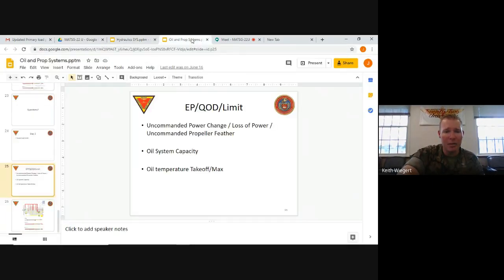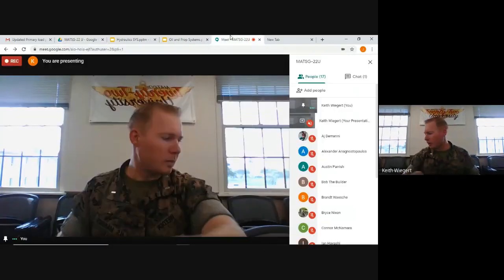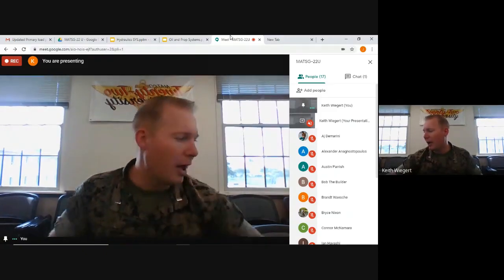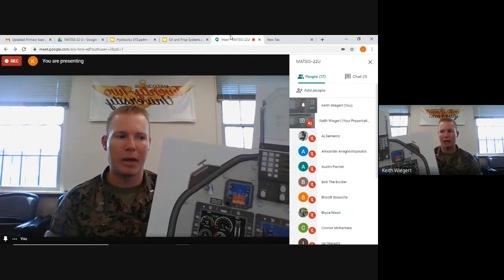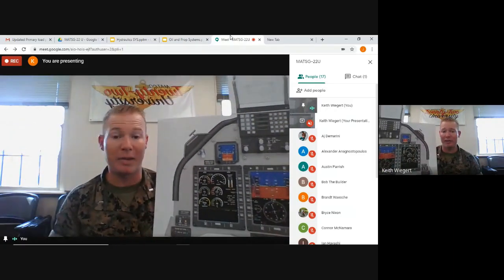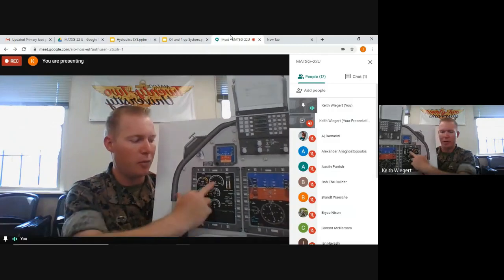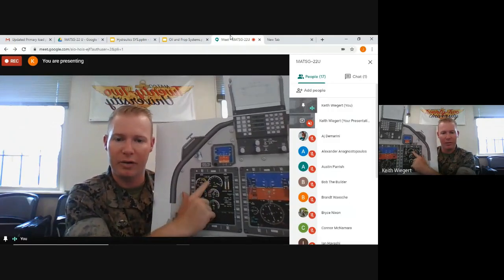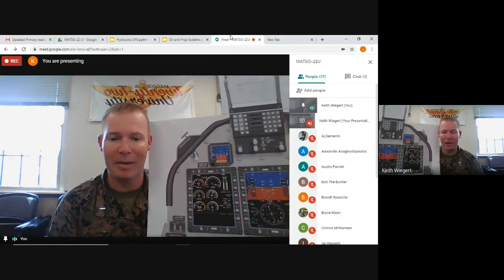For the question of the day, we have uncommanded power change, loss of power, and uncommanded prop feather, right? So all of this. First of all, let's talk about the EP, right? So uncommanded power changes. This is all three EPs in one, really, because all of the action items are going to be the same, right? But uncommanded power changes is exactly what it sounds like. We're looking at our torque gauge. The torque gauge is going to be going up and down, and we're not going to be doing anything to the throttle, right? So that's your uncommanded power changes.